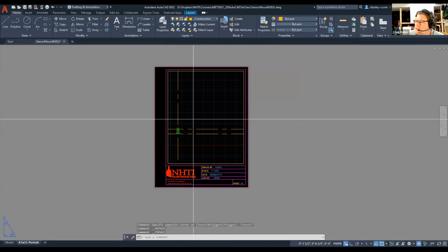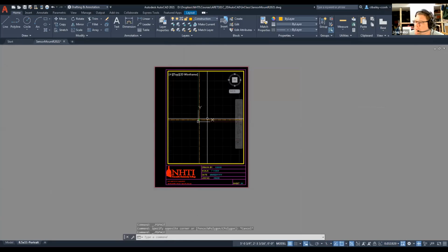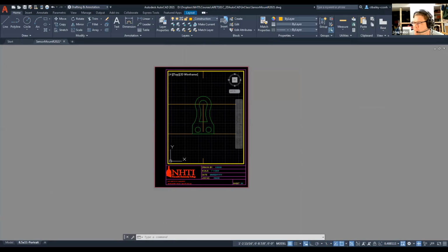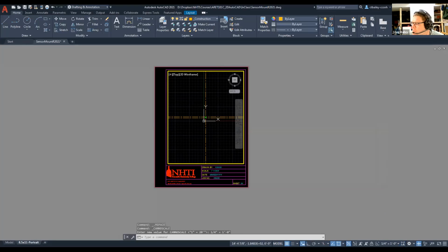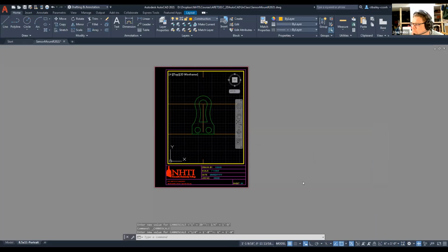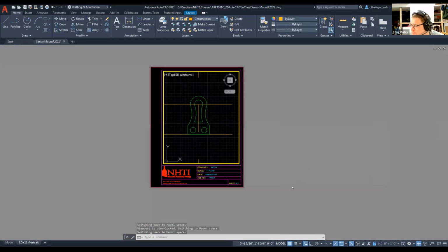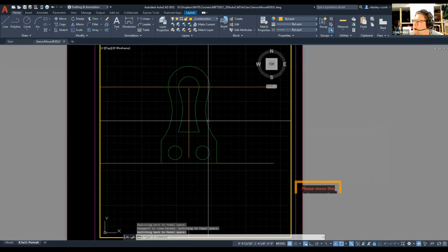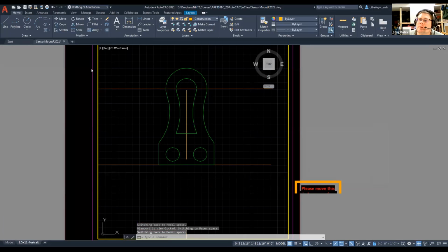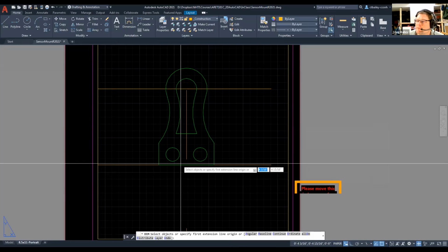If you double click into the viewport and you zoom around with your mouse, you're looking at the model space. And now what I'm doing is I've got it close, and I'm gonna go down to the system tray and select my scale. 1/4 inch doesn't work. I think we're gonna go to 6 inches. Yeah. And lock that. All right. And now that it's locked with the padlock, I can now zoom my mouse wheel and it doesn't move. And at this point, I'm going to just do some rough and dirty dimensions.